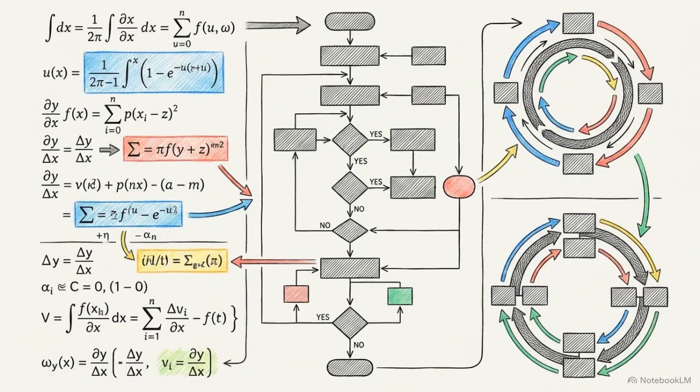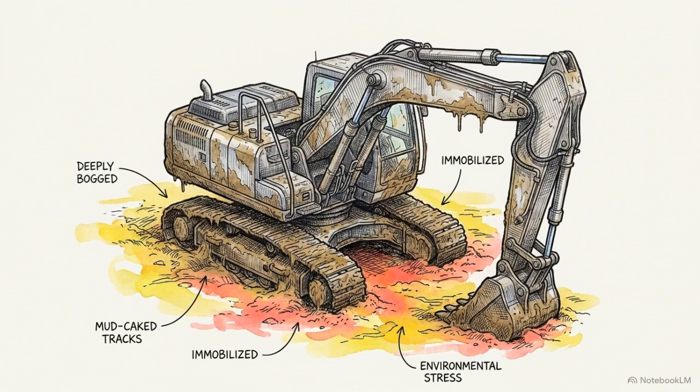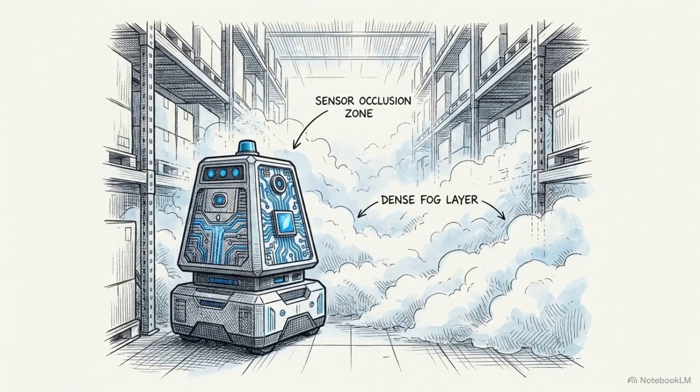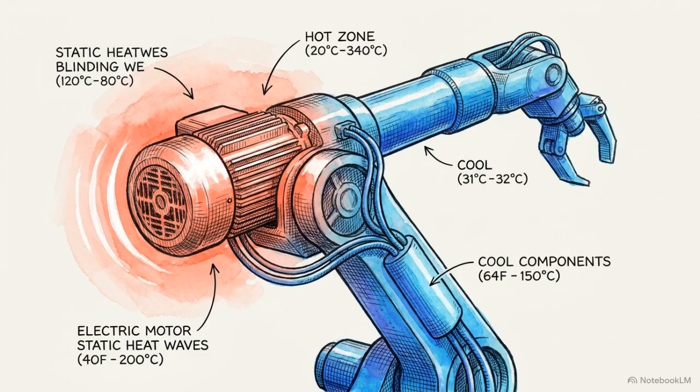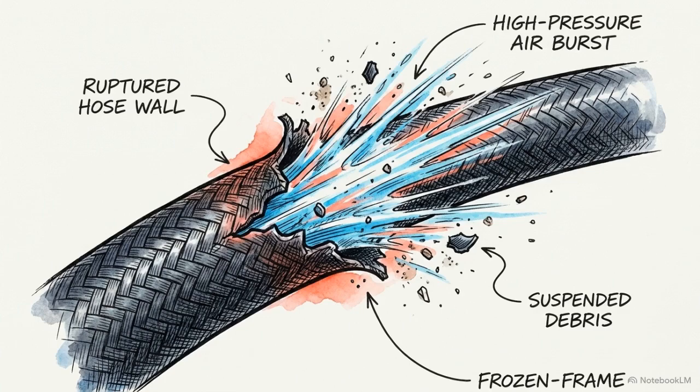While the feedback loop is theoretically perfect on a whiteboard, real-world deployment stress tests these hardware components, exposing severe physical limits. Sensors have specific environmental vulnerabilities. Sudden drops in lighting or unexpected physical occlusions can blind a vision sensor, cutting off the data supply to the controller. Actuators suffer from physical degradation. Electric motors overheat when operated continuously under high loads, and pneumatic systems lose massive amounts of efficiency if tiny air leaks develop in the lines.